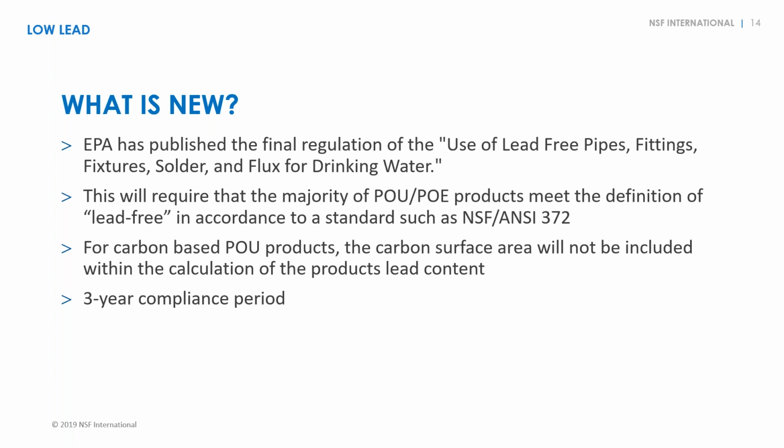One thing also to note is that for products that are certified just to standard 61, which is not necessarily point of use products, it's for more point of entry and also faucets and everything else, there is a low lead requirement within it already. So products moving forward certified to standard 61 will meet this definition.